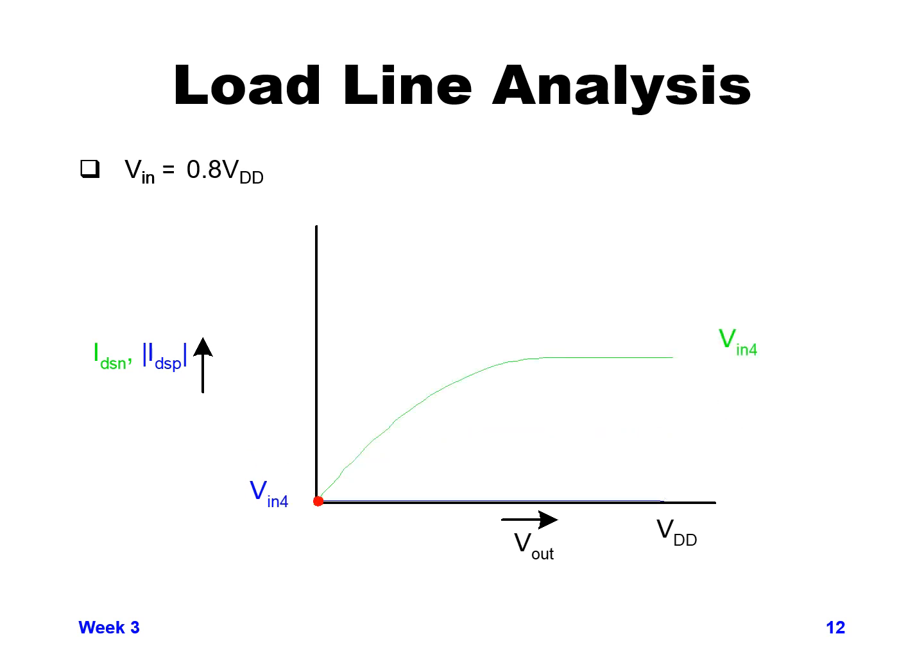And when we get to 80% of VDD or Vn4, now it's the flip. It's close to flipped of the 20% of VDD that we looked at, where at Vn4 the PMOS device is pretty much turned off, but it's still on a little bit, and the NMOS device is pretty heavily turned on.